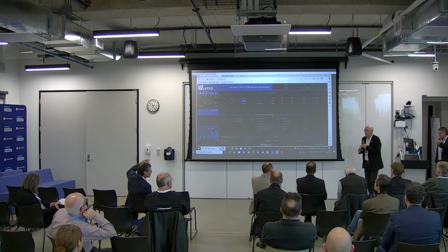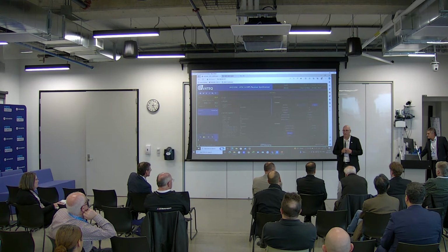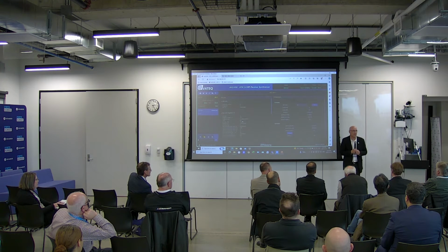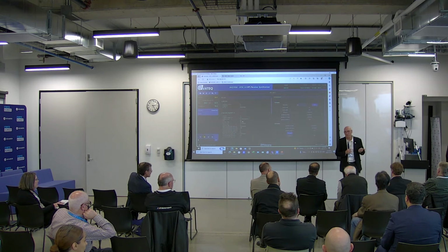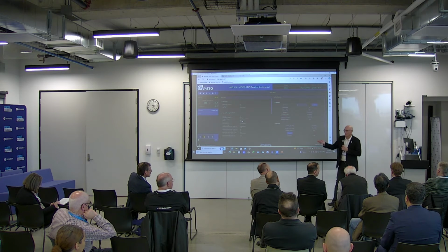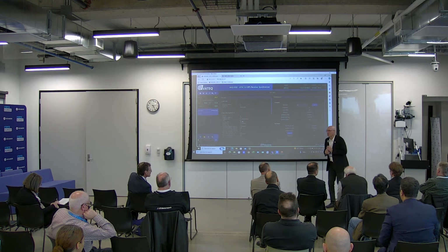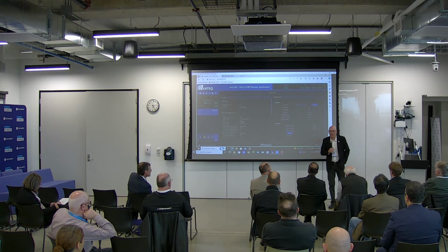Thanks, Vlad. The other thing that occurred to me, when we were talking about this BPS info, all the signaling in ATSC 3.0 and all of the data that goes out can be signed. The signaling is required to be signed. Any kind of interactivity has to be signed. We could sign the BPS info too, so it couldn't possibly be spoofed. So that's a possibility as well. That's a different systems architecture, so I have to think that one through first, because we have to deal with PKI and things like that. So it's an interesting nut to crack, but we'll figure it out.